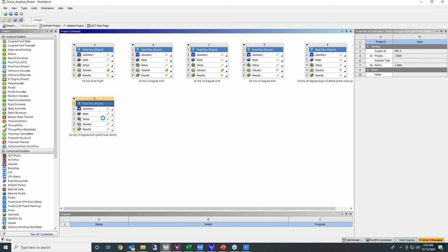So I'm going to go into Fluent like we saw before, and I'm going to change, let me pull up Fluent one more time. I got the license tied up there real quick. But basically I would go back into Fluent and change that unit vector on my inlet boundary so that now I'm going to do the cosine and sine of 30 degrees. I'm going to figure out what those unit vectors are for X and Y, edit those, put those into Fluent, and rerun it.